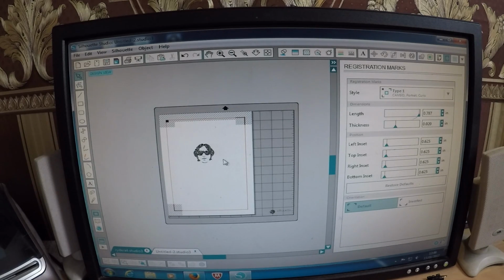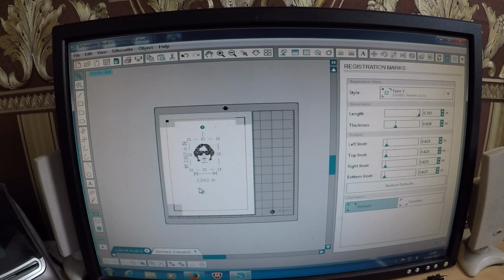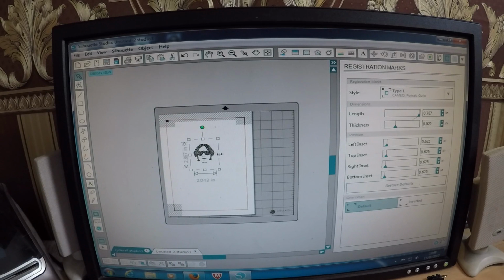So right, what I'm going to do now is just to click on the image and we get our box around it. These little square boxes here are the little adjustment windows. All I'm going to do is take a diagonal one. The reason why I take a diagonal one is because, as I hold the left mouse button down and draw this backwards, the actual image will open up in scale. If I choose one of the middle ones, it would pull the image to the side and widen it. Or if I pulled the top and bottom center squares, it would elongate the image, and that would throw everything out of proportion. So to make this image in proportion, grab hold of one of the diagonal buttons until the little mouse changes, hold your left mouse button down and just drag until we see it get bigger.